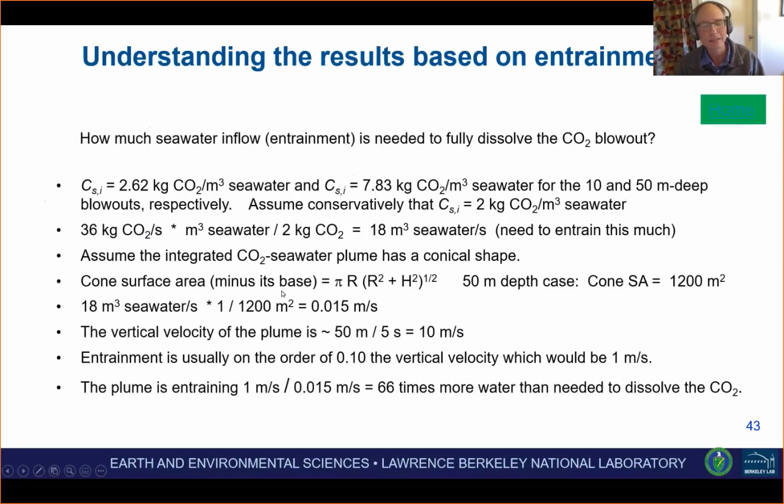If I look at the surface area of that cone in the 50-meter case, and the vertical velocity of about 10 meters per second, and knowing that entrainment is about 0.1 of the vertical velocity, I find that I could be entraining about 66 times more water than would be needed to dissolve that medium-sized bubble.